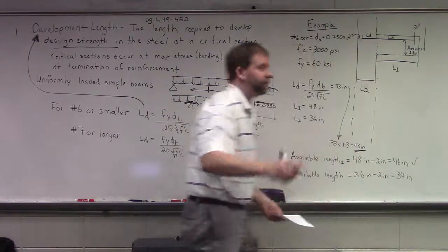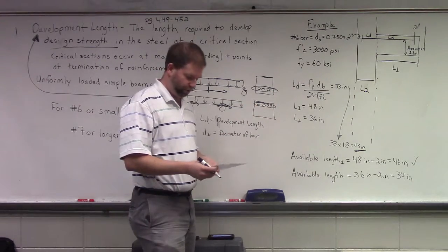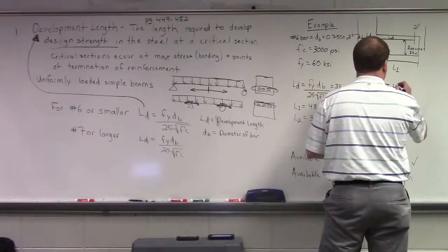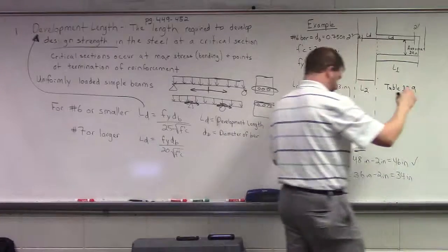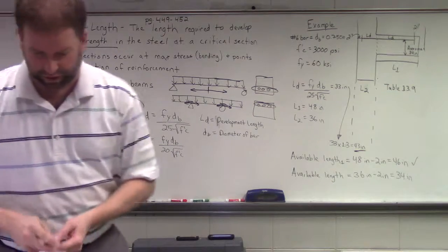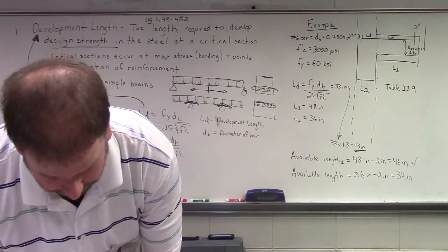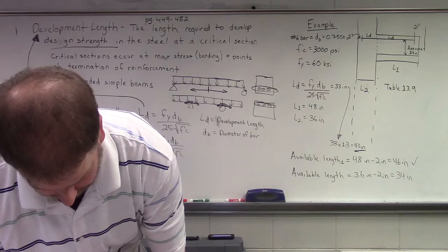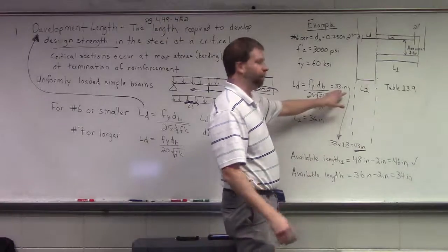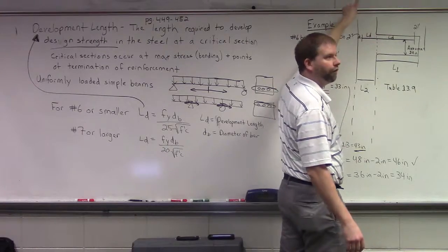The last thing that I just needed to tell you is these values, okay? I showed this to you once so you understand where the calculation comes from. You can find it in the table, table 13.9, okay? Do you have a page number? 451, I think. Somewhere between 449 and 452. So then, 34 doesn't work. No, 34 does work, because it's not top bar at that point. It has concrete over the top.